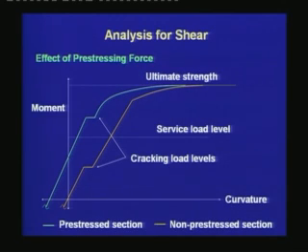We had seen these curves earlier, that for a reinforced concrete beam, the moment versus curvature curve passes through the origin. After cracking, there is redistribution of stresses, there is increase in curvature, and then we observe nonlinearity in the behavior due to the nonlinearity of concrete. Once the steel yields, then we observe the nonlinearity of the steel as well, and gradually the curve tapers off